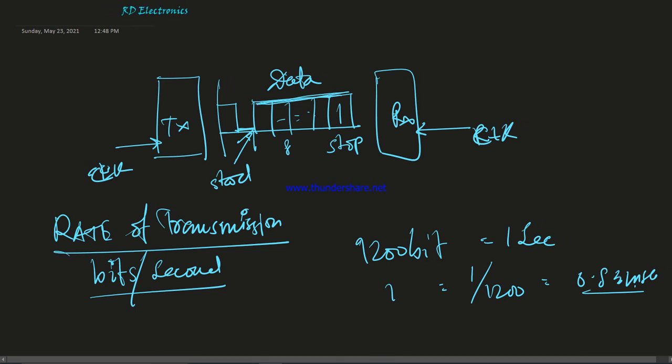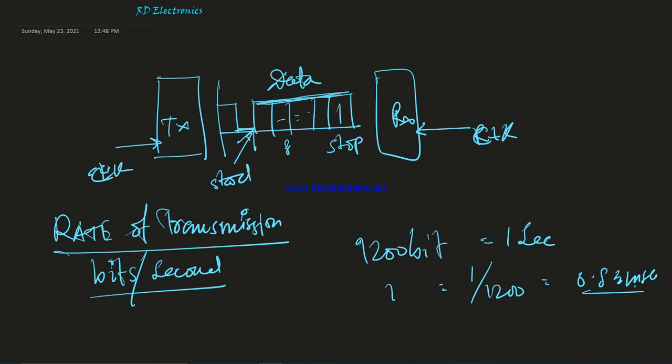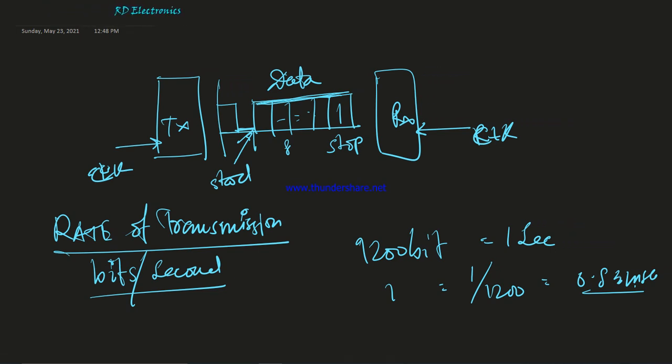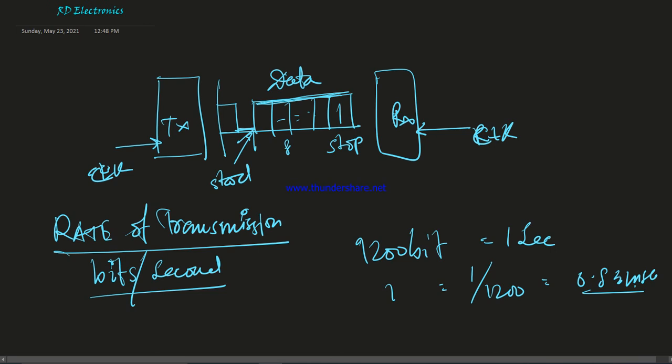And there is also another bit used in serial transmission, which is known as the parity check, but not all the time can we introduce the parity check in serial data transfer. The parity check bit is used because during transmission various types of error can occur. For example, data bits may change because of noise, or can be misunderstood by the receiver because of differences in the receiver and transmitter clock. So these errors need to be checked.